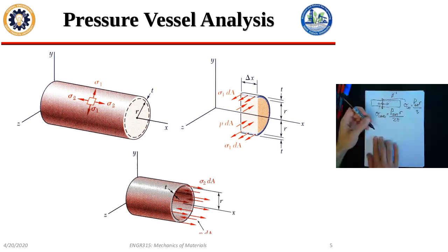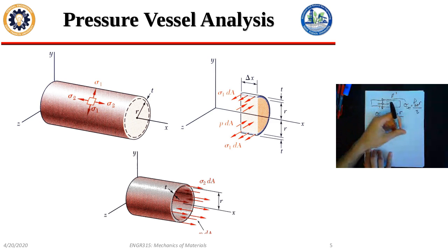So I wanted to plot that on a circle. I wanted to draw Mohr's circle based on that. Well, one of the things I need to do in order to draw Mohr's circle is know the center, and I need to know the radius, right? The center of Mohr's circle is what? How do I get the center of this thing?